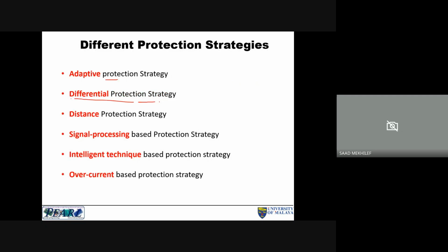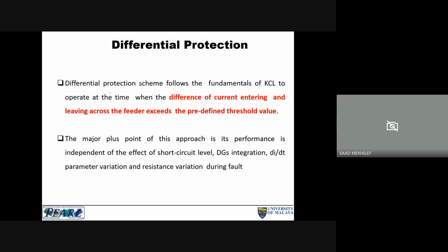The other one is differential protection. The differential protection scheme follows the fundamental of KCL, Kirchhoff's current law, and operates when the difference of the current entering and leaving across the feeder exceeds the predefined threshold. So this is the basic principle. It has an independent effect of the short circuit level, though DG integration and di/dt parameter variations are also quite important.